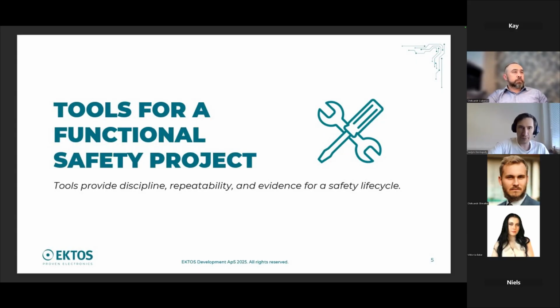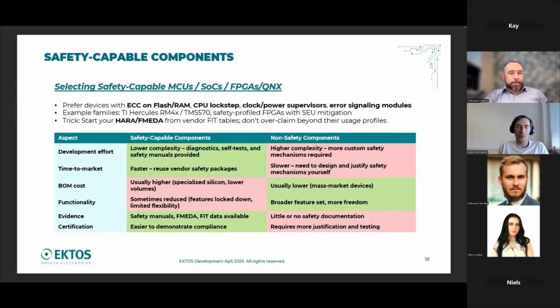Okay, so if you have tools, now we have to think about some tricks and techniques. First of all, when you develop your system, consider key components and look into safety-capable components, specifically for complex components like MCU, system on chip, FPGA, or if you select an operating system.